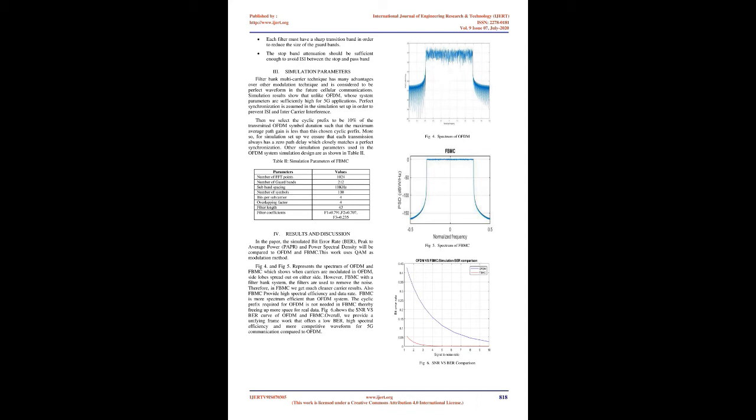Prototype filter design. Digital prototype filter design is based on Nyquist theory. The design criterion states that the impulse response of the transmission filter must cross the zero axis at all the integer multiples of the symbol period. The condition translates in the frequency domain by applying the symmetry condition about the cutoff frequency, which is half the symbol rate. Later, a straightforward method to design a prototype filter is to consider the frequency coefficients, f, and impose the symmetry condition.